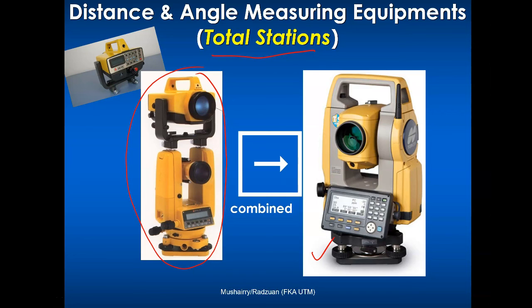Obviously, if you look at the panel down here, a total station has more functions and more interaction with the user. And you will be using a total station in your work, because to keep up with technology, I think it's appropriate that you use total stations rather than a theodolite and an EDM, even though we do have them.